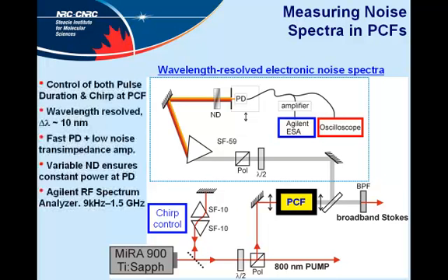Okay, so it's wavelength resolved noise measurements, and we're going to look with a spectrum analyzer over this 9 kilohertz to 1.5 gigahertz bandwidth. If you think about this, 9 kilohertz is 33 microseconds. So if you have a dwell time that is less than 33 microseconds, then you're within this band. So those are the noise features that are relevant to microscopy.